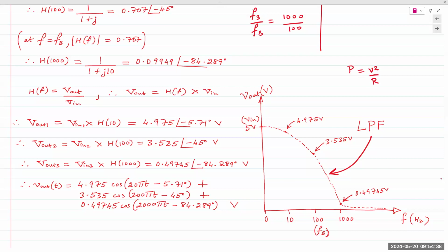That is the point where, if you have a filter circuit, remember, the filter's job is to block an incoming signal, right? But if it's right at the break frequency, it's not going to go all the way to 0. Instead, it's only going to go to 50%, meaning the incoming signal is dropped to 50%. So we design our systems keeping all of those facts in mind. Even though we do obtain 50% output at the break frequency, we consider it to be blocked.